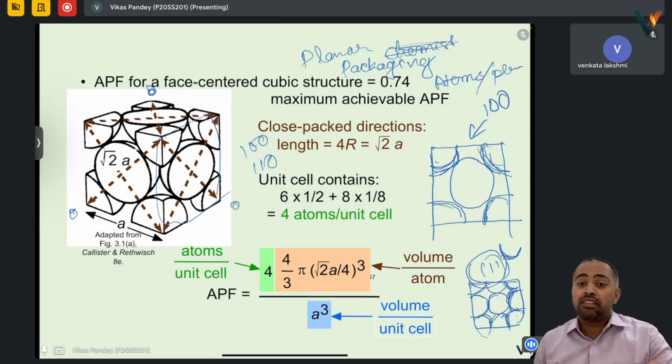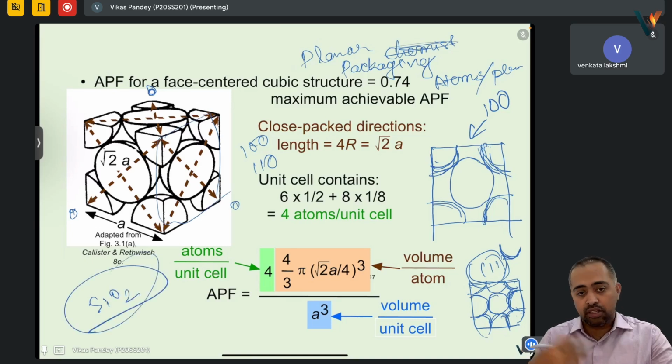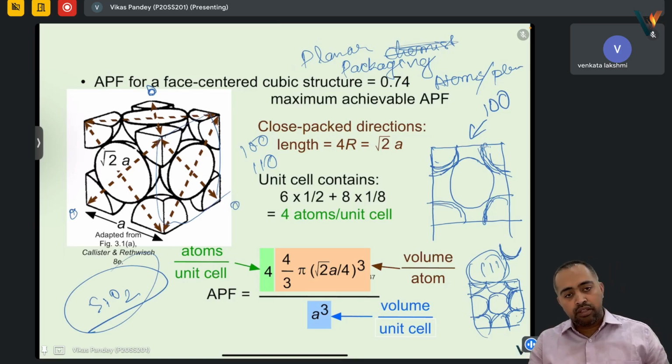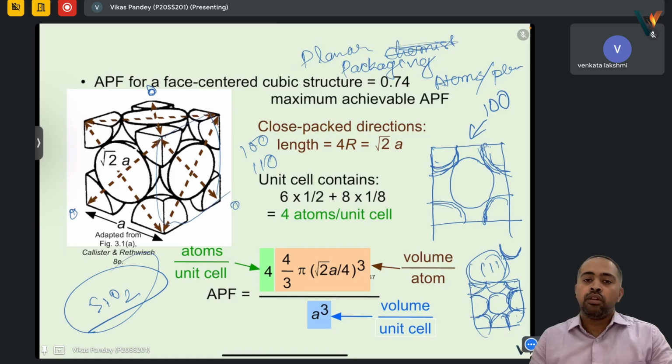But at the same time, it has this advantage that if we are thermally growing silicon dioxide, SiO2, the 111 plane yields faster SiO2. The reason being, again, it has more silicon closely and densely placed. That is why more silicon is available and easy oxidation is possible. So in some cases it is lagging behind, in some cases it is faster.